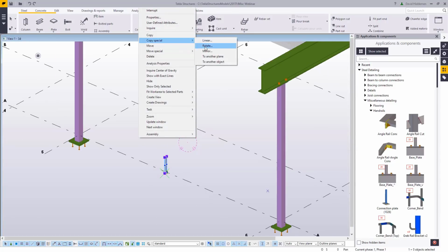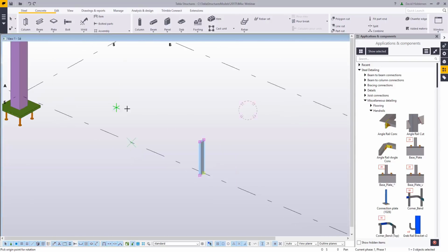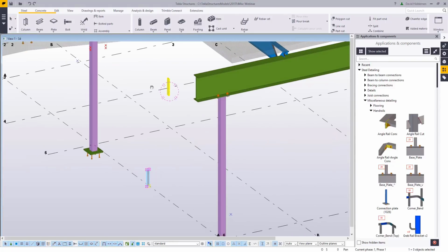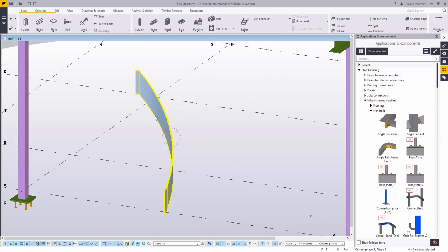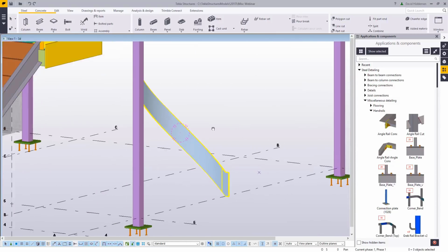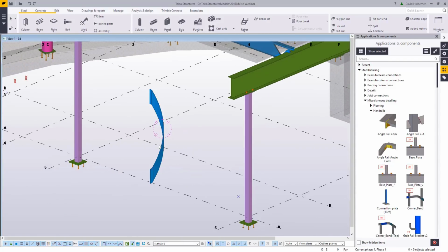If I copy this to a different elevation and rotate it away, so I'll just go 4 feet away in the Z at a 90-degree rotation, we can use that same functionality to join two plates together that aren't even facing one another. So that creates a curved web vertical plate that would be perfect for something like a stair stringer. That type of functionality is that easy to use. Create a little starting point, little ending point, tell them to connect together.